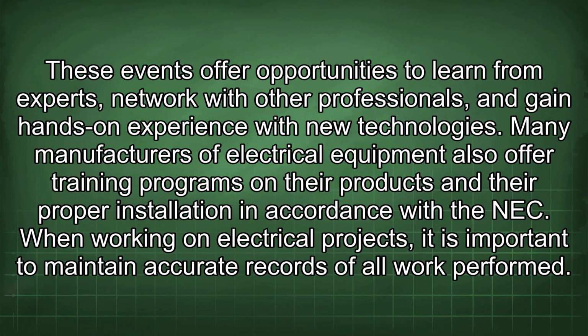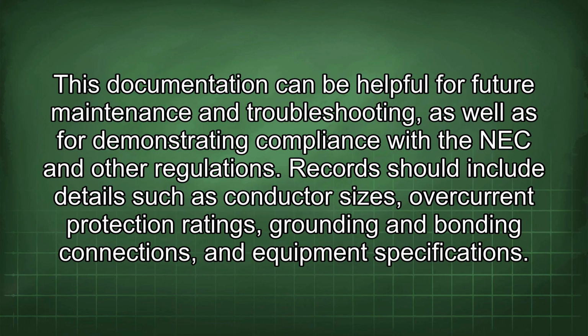Many manufacturers of electrical equipment also offer training programs on their products and their proper installation in accordance with the NEC. When working on electrical projects, it is important to maintain accurate records of all work performed. This documentation can be helpful for future maintenance and troubleshooting, as well as for demonstrating compliance with the NEC and other regulations. Records should include details such as conductor sizes, overcurrent protection ratings, grounding and bonding connections, and equipment specifications.